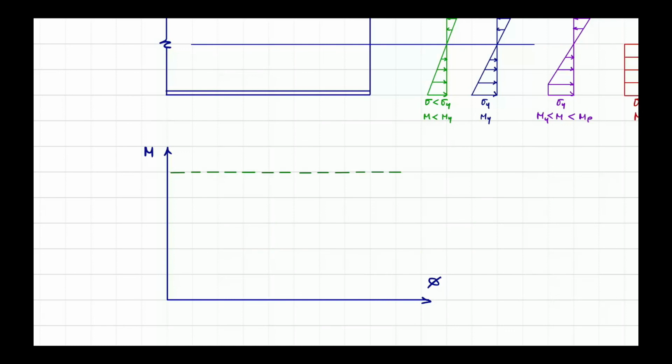If it is a concrete cross section, okay, I can understand that there is something I should talk about. But for a steel cross section, you just have compatibility. You just keep changing the phi values, and then you get the moment. You plot moment and phi. So I don't think I should elaborate on this little detail, but I'm going to show you the picture.